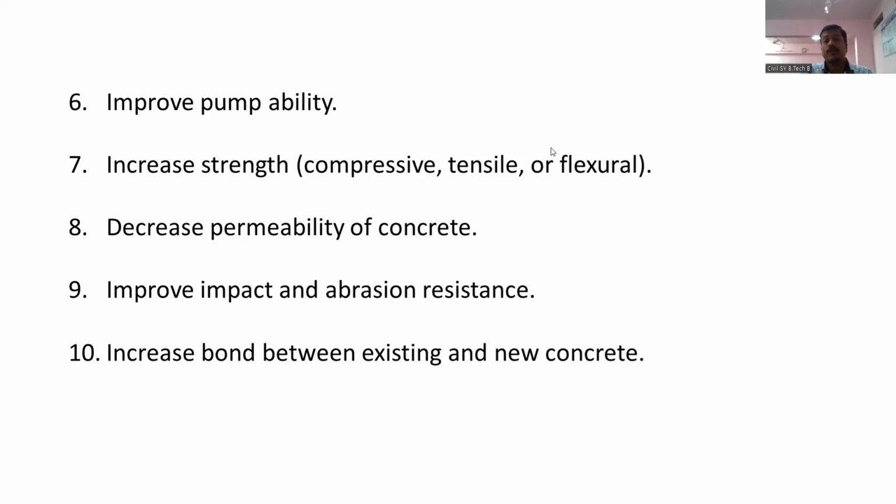For that we require highly workable concrete. You can make your concrete highly workable by using admixtures without compromising the water cement ratio, or even by reducing the water cement ratio. You can improve the workability of the concrete by use of admixtures.